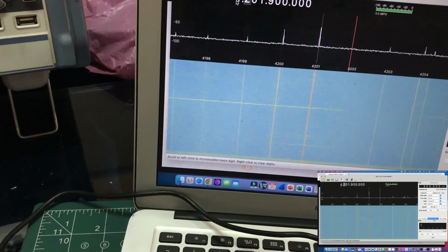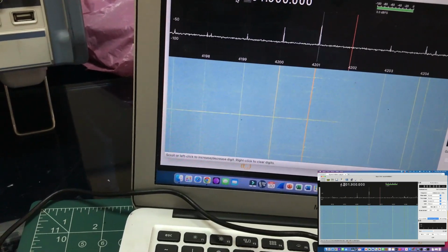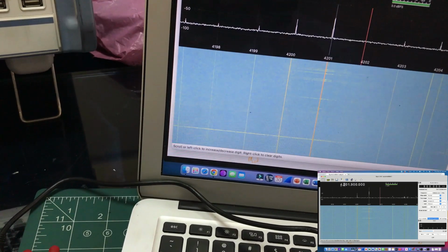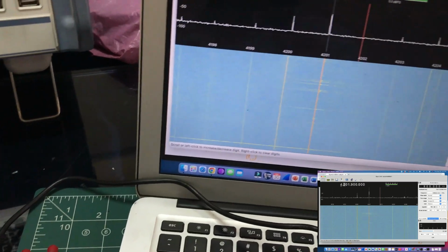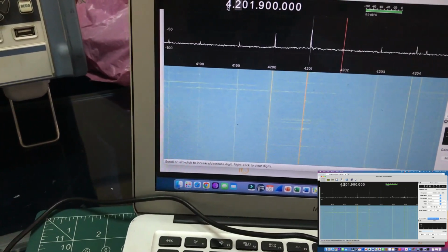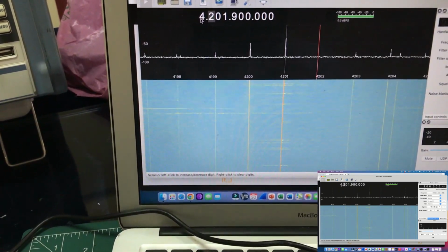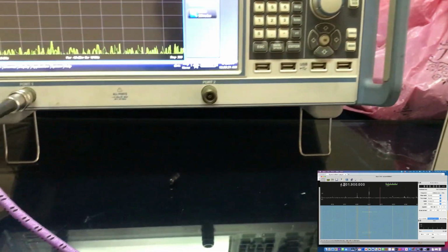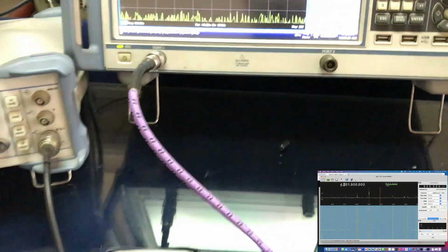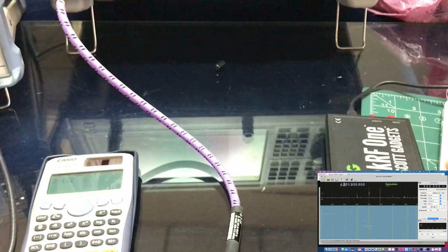You need two function generators and a spectrum analyzer to look at the performance of your mixer if you don't have 3-port or 4-port devices available. This is probably the cheapest way you can check your mixer. If you also had two generators, you could have performed the same thing using a spectrum analyzer. But I was just giving you one idea that you can use.